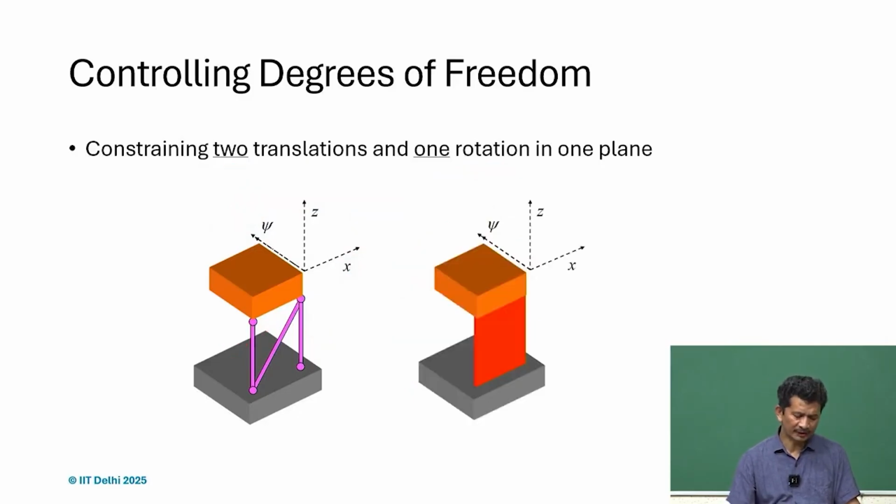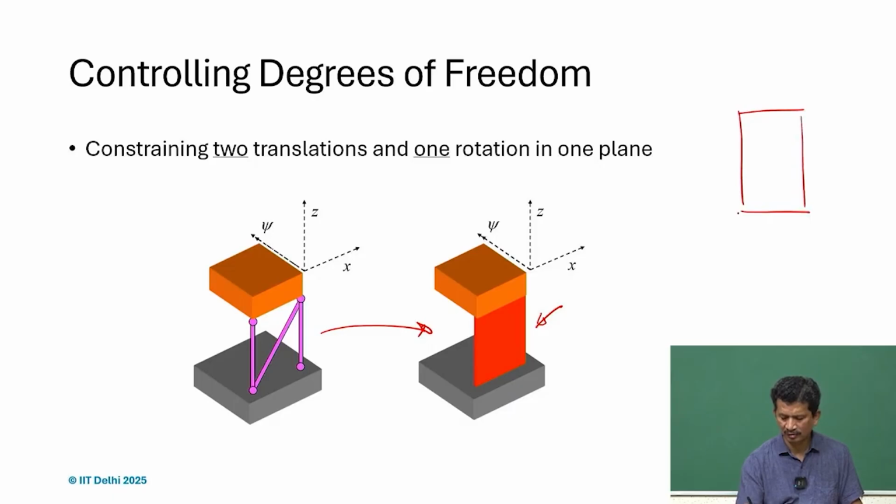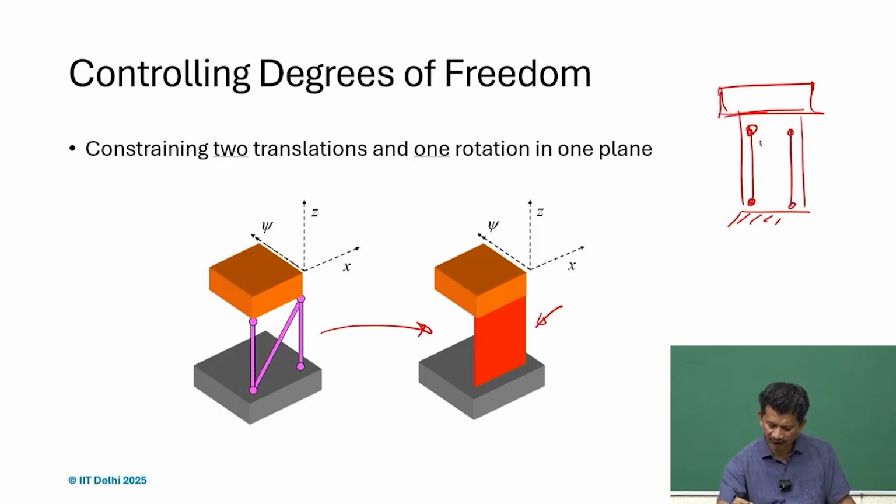And what we realize is that if we are able to do that, we can simply replace this entire construction with the sheet flexure, or many times we call it leaf spring. So, this is the equivalent. If we just take any sheet flexure and constrain it with the body, what we realize is that it is equivalent to two parallel constraints and one diagonal constraint.